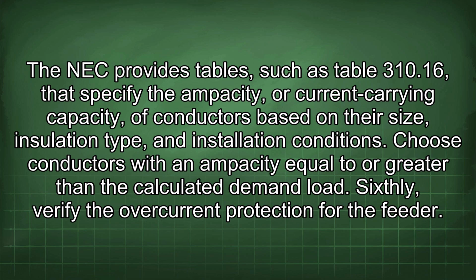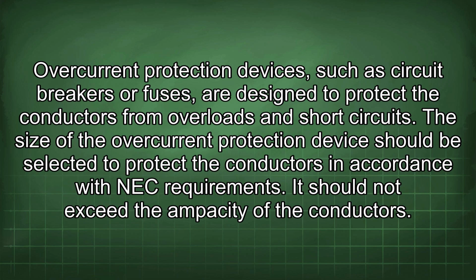Sixthly, verify the overcurrent protection for the feeder. Overcurrent protection devices, such as circuit breakers or fuses, are designed to protect the conductors from overloads and short circuits. The size of the overcurrent protection device should be selected to protect the conductors in accordance with NEC requirements. It should not exceed the ampacity of the conductors.